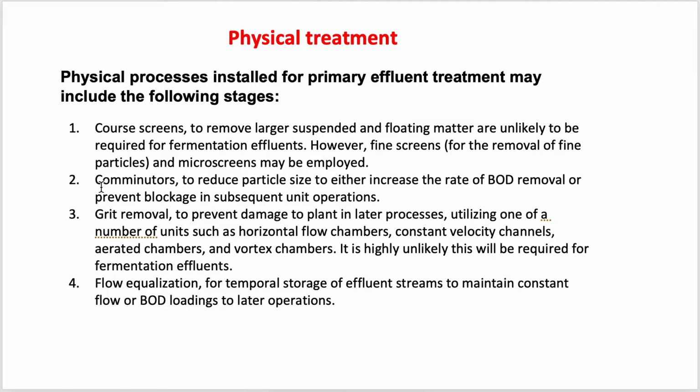Then comminutors, they are actually grinders. Comminutors are used to reduce particle size, to either increase the rate of BOD removal or prevent blockage in subsequent unit operations. I mean, if the particle sizes are too big, they may block the subsequent operations of the treatment process.